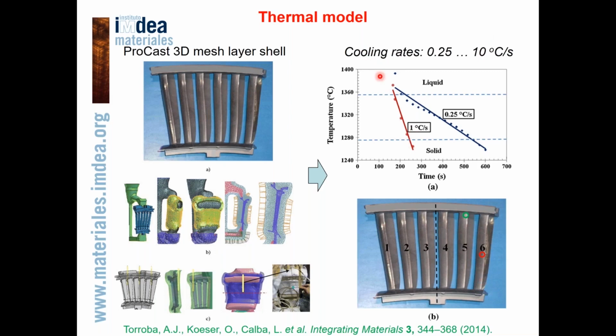Here one can see two typical temperature time plots theoretically estimated for two points of the nozzle guide vane, which are cooled at 0.25 degrees per second and 1 degree per second. More details about development of this Procast model and its validation can be found in this joint article published with our partners.